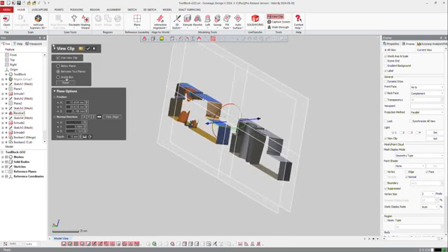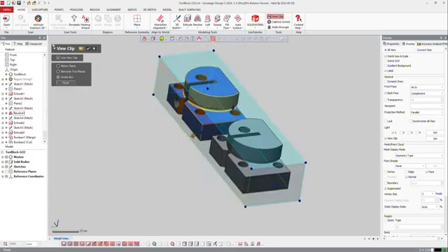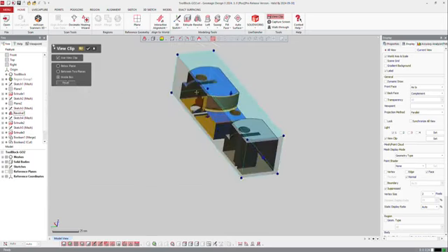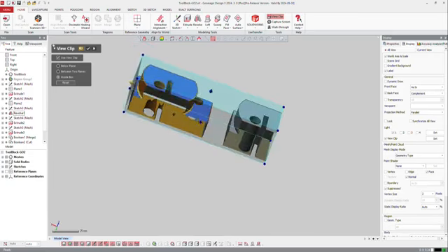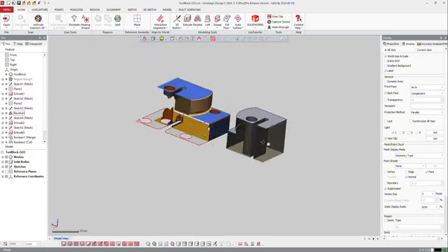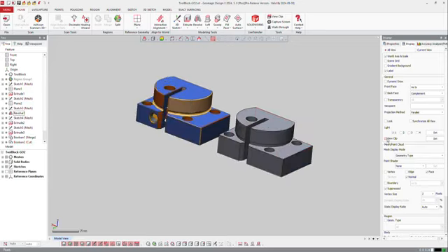The last option is to go inside box, and then here you can select the box and shrink it like that. Of course, when you press apply or OK to the function, the view clip is still applied. You can anyway go to view clip and activate or deactivate it, and activate it again. It remembers the parameters.